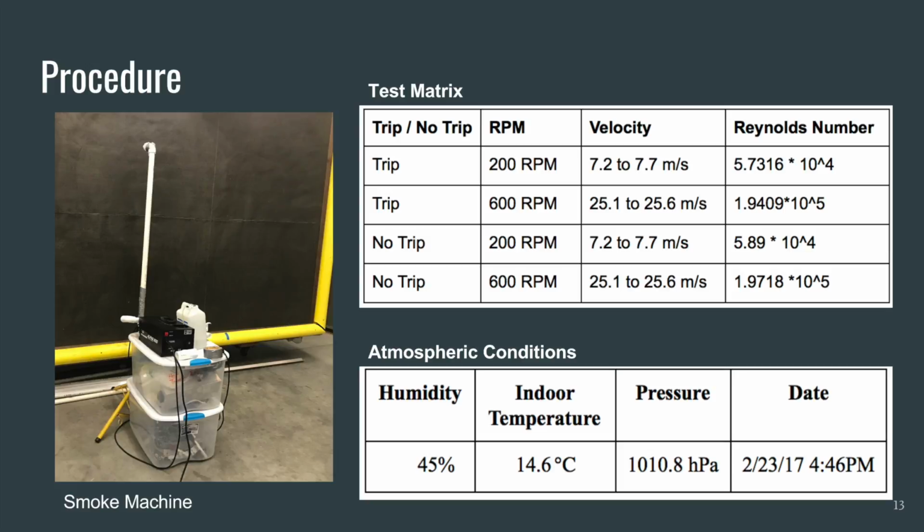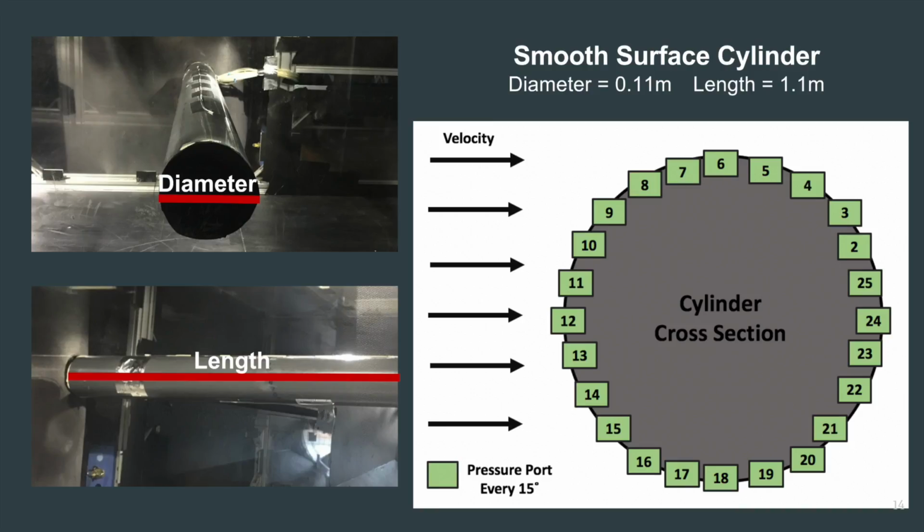Before starting up the wind tunnel, the team ran a final safety check. Each team member was in charge of operating either the smoke, laser, lights, or video. The smoke machine shown in this video produced smoke that was circulated through the tunnel. The laser and floodlights shined down onto the cylinder. The combination of the smoke and lasers provided flow visualization. Throughout testing, a team member checked the cylinder and taped items to ensure everything was secure.